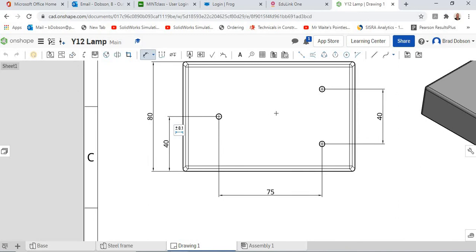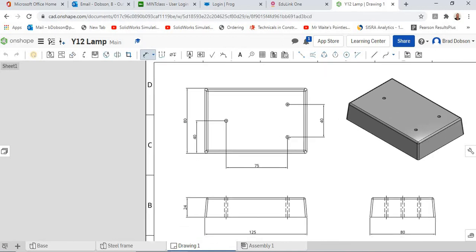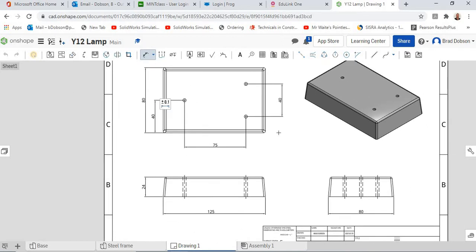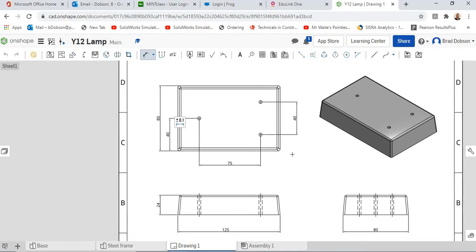So we're going to our basic dimensions again. Things like that we assume, if you're not putting otherwise, you would assume that those are in the centre, which is why I tend to draw that centre line on. Quite often you don't dimension from edges to centre of holes. It's always across the centre line realistically, so that's why I'm not adding anything on there.